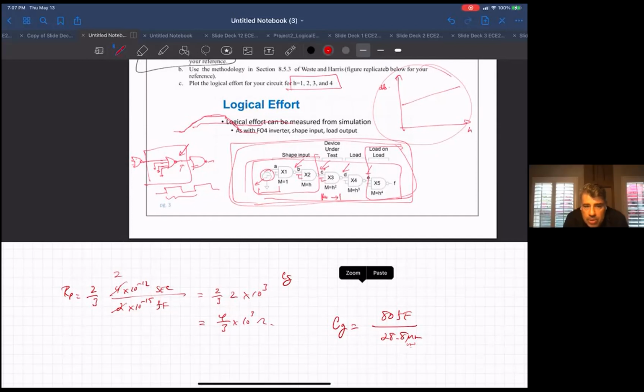Okay, cool. You guys have another week to crank on this thing. Again, I think I've mentioned this before, and given that you're unlikely to have funky logic circuits like 4-input NORs or something really slow, when you put this together and simulate, make sure you're getting full rail-to-rail